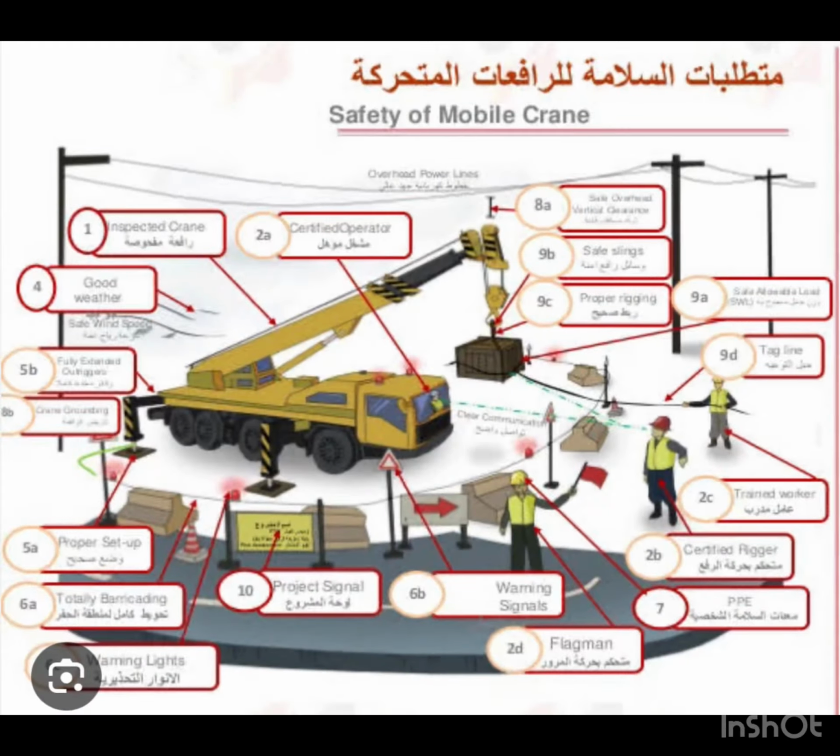What are the requirements for a crane lifting? Crane position should be on firm ground with outriggers fully extended and should be on a rigger pad. Make sure the tires are off the ground. Ensure certified rigger and crane operator are being used. Ensure safe loading indicator is working. Inspect the crane for any leakage before working.